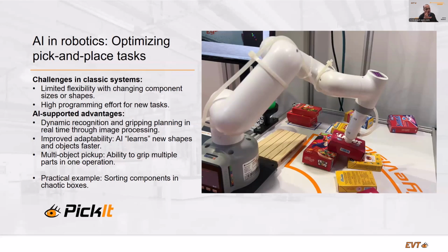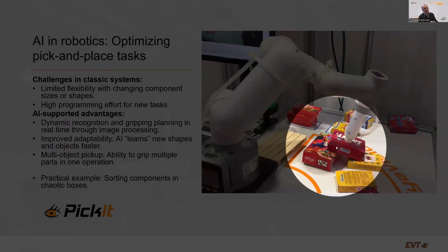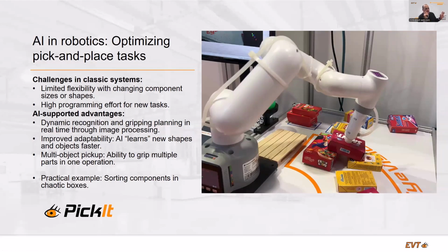The combination of the AI tool for the recognition and the point cloud finds the right gripping point. In this case, that's why I have used this image. You see the boxes are not flat, they have any angle. So you get the angle out of the point cloud, whatever angle it is. This is mandatory to have a good grab point and the right orientation for the gripper. If this is, let's say, a small demo tool gripper, or a gripper from, let's say, Schunk or some of the other manufacturers, it doesn't matter. The important thing is that you get the information about the orientation of the part you want to grip, and of course to get it with a perfect accuracy to grip it from the table.